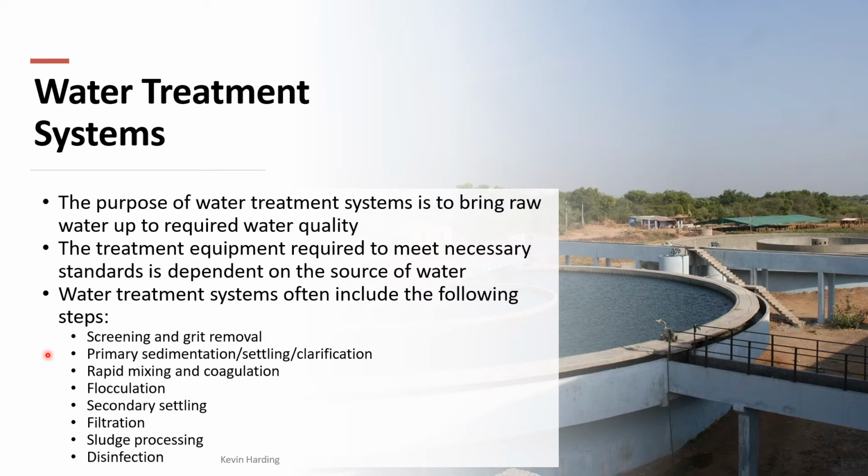Simply like that diagram on the right, water will enter and the solids will settle out. You can't see it in this diagram here, but on the right-hand side you can see one of these empty ones. Water will come up through the middle here, and the liquids will come in through the system. Water will come in here, flows over, and the solids settle to the bottom. At the bottom there's a solids removal system.